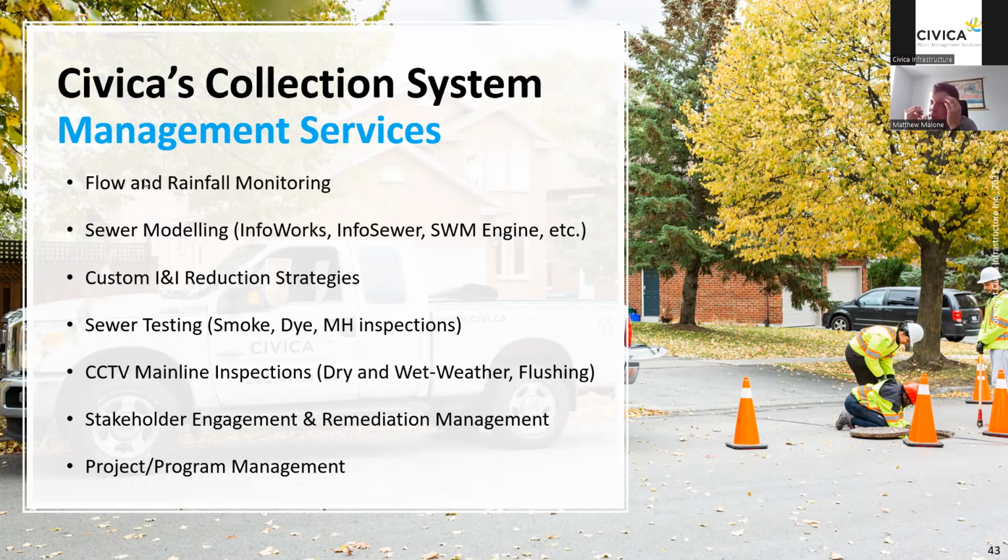So Sean, there's a question about rain gauges on shortcut grass. Yeah, we do put quite a few rain gauges on roofs as well. It's typically easier for access, and it's tough to find a nice green space that's not like a park where people will go in and mess with your rain gauges. But roofs are actually not great. The thing with roofs is that they're really susceptible to wind as well, which makes the monitoring of rainfall not as ideal.